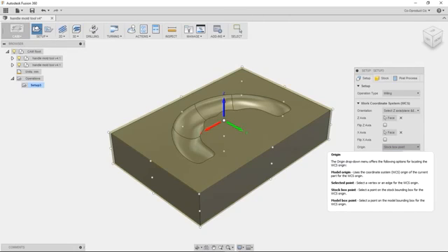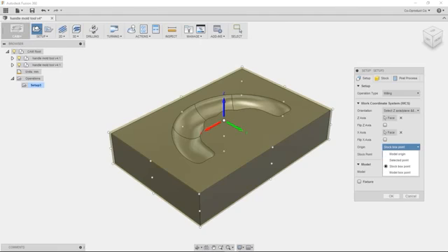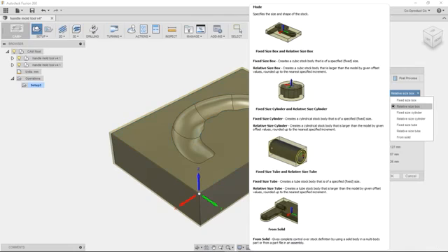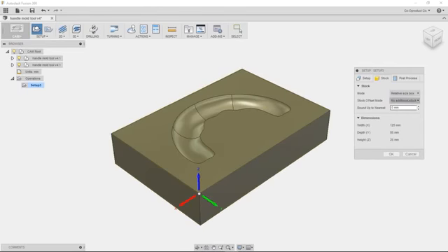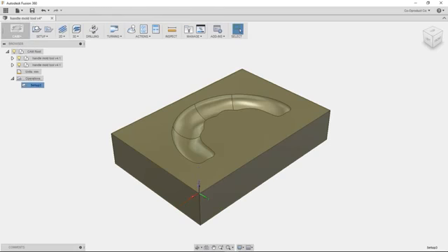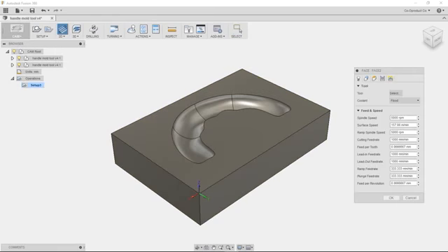When you're setting this up on your CNC machine, the machine needs to know where the origin of the material is. So if we select the origin as a selected point, I'm going to select this front corner edge here as the origin. Now if we select the Stock tab and then select Mode Relative Size Box and then Stock Offset Mode to No Additional Stock, we're going to use our block, which is width 125, depth 85 and height 25. Click OK.